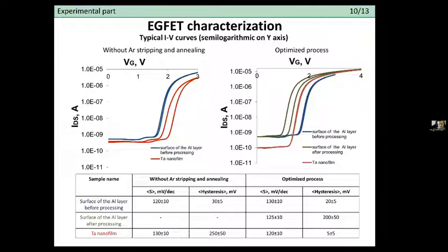So the aluminum surface preparation step also introduces some hysteresis into the structure, but it is cleared when the sensitive surface deposition is carried out. So the finished structure has very low hysteresis value, which has a lot of influence on the stability of the sensor characteristics.